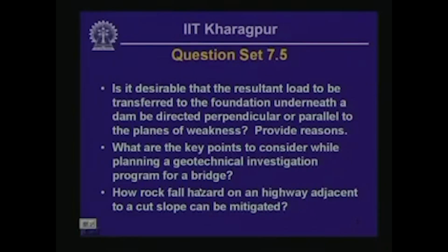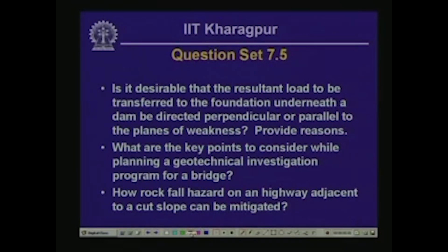So, we need to have a very clear notion from the geotechnical investigation that precedes the bridge design of what is the variability of the contact between the non load bearing overburden and the load bearing foundation soil or rock. Now, in order to illustrate the problem, let us consider a case like this. Let's say the bedrock surface is weathered in a very undulated, very irregular manner.